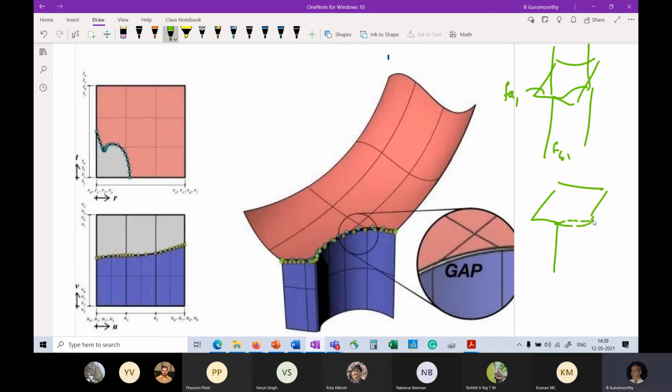It is on one surface and another surface is that, and therefore you will see this gap. So this is I1, this is I2, and the intersection curve on one face looks like that. The intersection curve on the other face looks like this. So in some sense, this does not satisfy your watertight requirement that my object must be watertight, because it is violating the condition. This edge on this face does not lie on any other face, and this edge on this face does not lie on any other face, and therefore it violates your first check for validity.